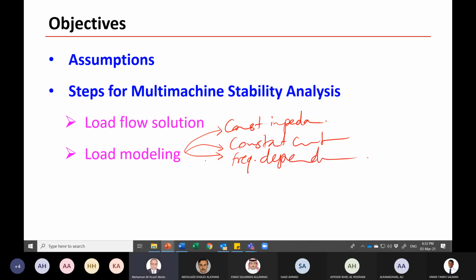A lot of representation of constant power. A lot of load representation methods that you can use, and this is exactly the case in real life. And maybe some loads can be represented by constant impedance. They have resistance, reactance, and that's all.